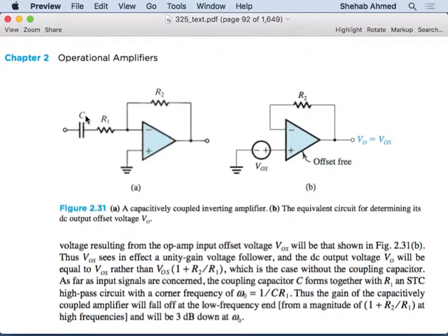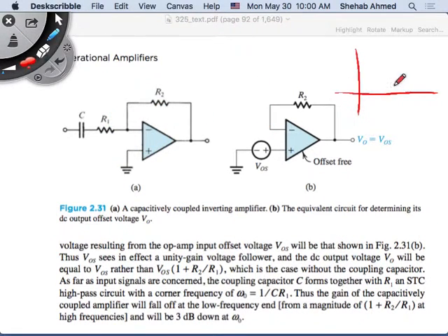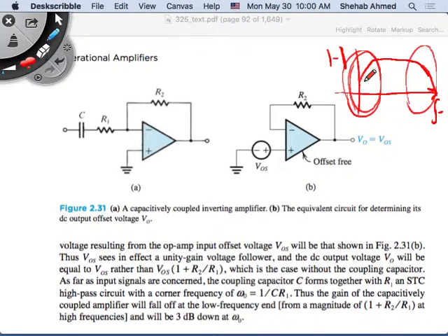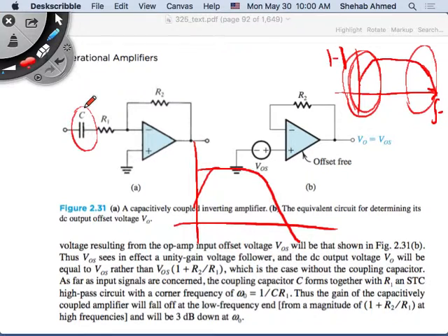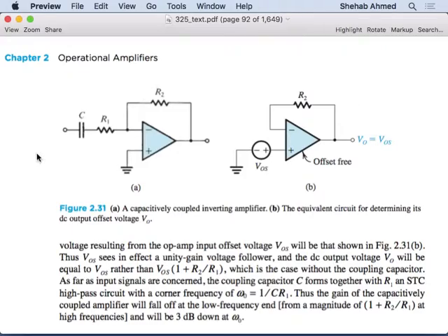Remember the first chapter, we talked about capacitively coupled amplifiers and how they dealt with the frequency response of my circuit, right? So they made the gain versus frequency look like something like this. They had attenuation here and attenuation at high frequency. And we said that this is due to the fact that they're called capacitively coupled amplifiers. The op-amp inherently is DC coupled, meaning it has a characteristic like this, so it does not attenuate at DC. That's why you would add this externally if you want to deal with the offset voltage. Everybody's good with the offset voltage issue?